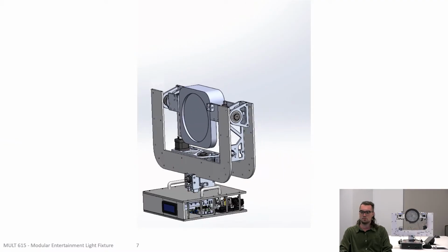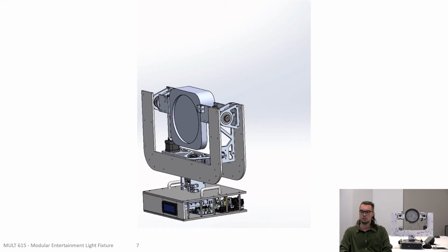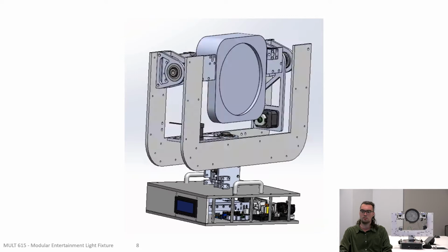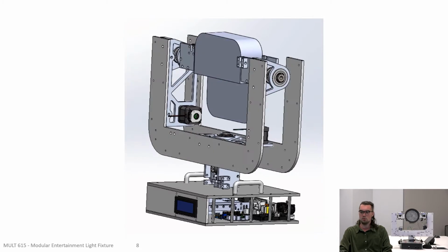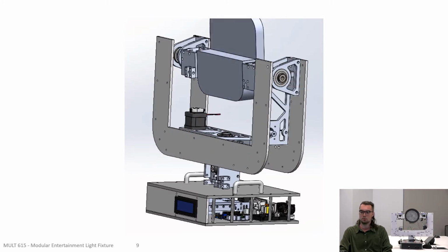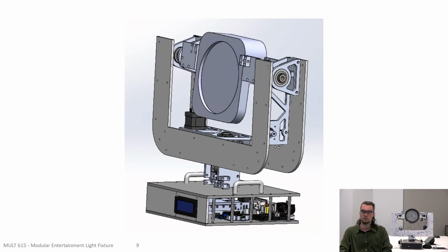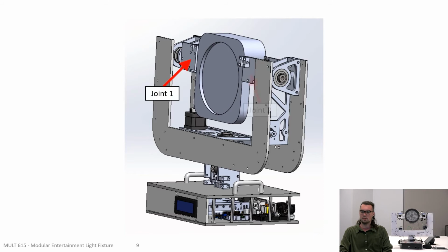The complete prototype shown here is a full-size model of a stage light with the separable joint included, demonstrating the ability to easily switch between head units in the field. It pans 540 degrees about its vertical axis and rotates 270 degrees about its horizontal axis. These are standard ranges of motion in the entertainment industry. All three joints are the same design. This aids in end user servicing as well as faster manufacturing and achieves our ease of use repair goals.